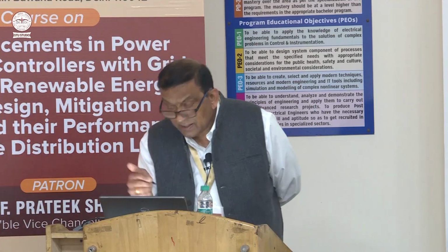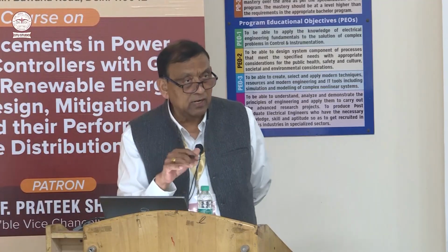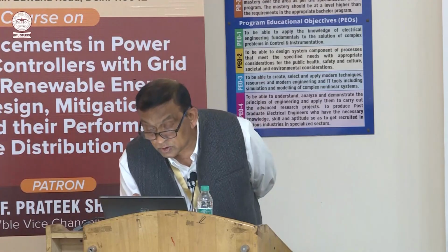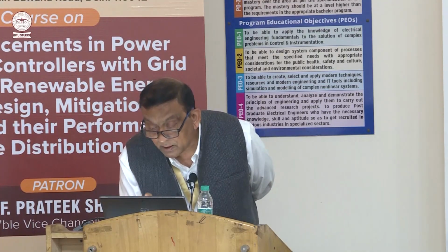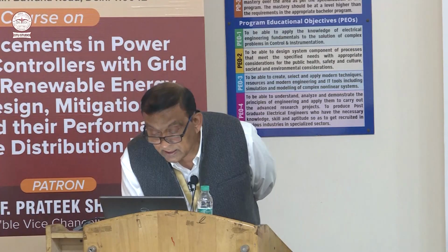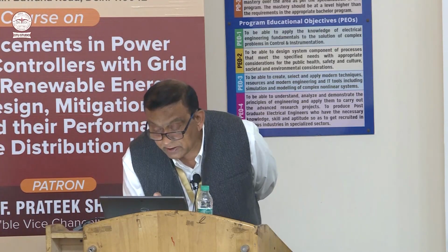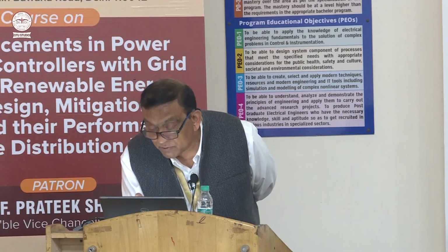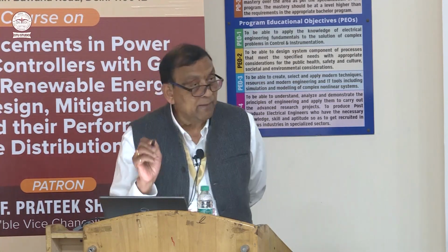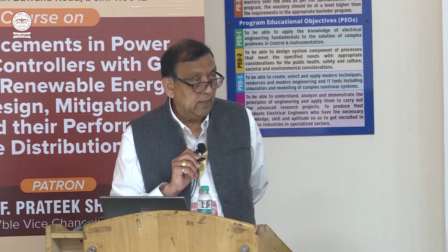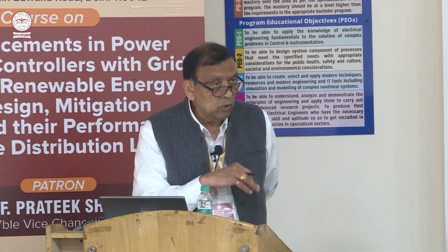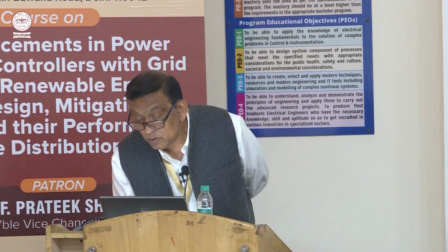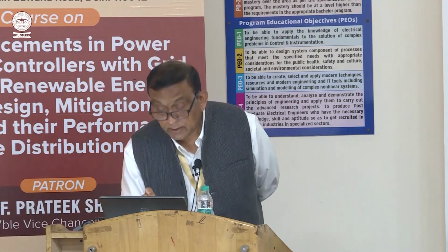You may think that it is difficult to analyze this thing, but it is not very difficult to analyze those transformers. Suppose we analyze this polygon transformer, right? In this polygon transformer, you can see on the primary side, you have delta, this winding, and this winding, and this winding. They are on the same leg of the transformer. And the sum of magnetomotive force should be 0 in that leg. So this is how you can write this equation, right?